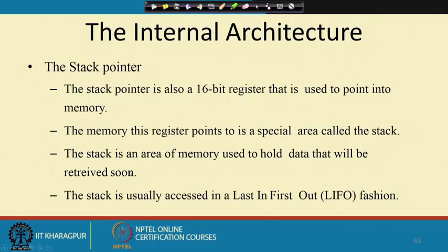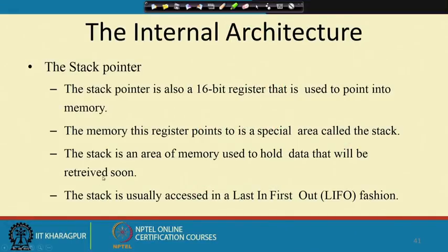So, this may be that return address, or it may be some parameters that we have passed from the main program to the subroutine. So they can be retrieved from the stack, and it is usually accessed in a last in first out fashion.